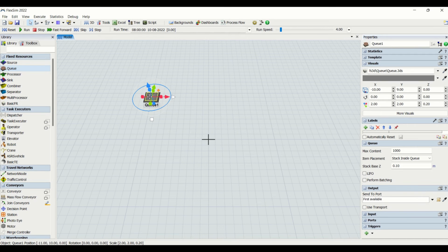A buffer is a storage area between two entities where we can store our produced parts or the parts which are going to get produced. So a buffer can be used for raw materials, or for finished goods. It depends on the modeling logic where we need to use Q, that is buffer. Q has its own set of properties which we will be learning and understanding.